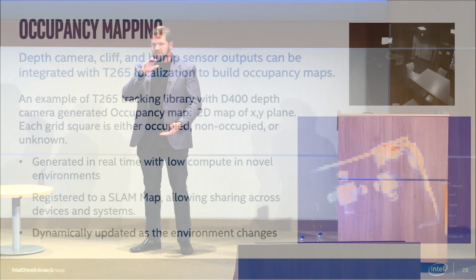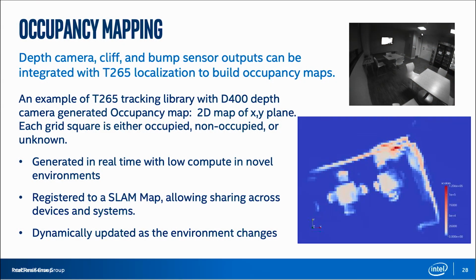And internally, this is a 3D representation. Only in the very end, we slice the 3D map at the height of interest of the robot to obtain this 2D occupancy map. And the different fields here, the meaning is they have a probability between free and occupied, 0 to 100. And this can be in the next step used for the path planning.